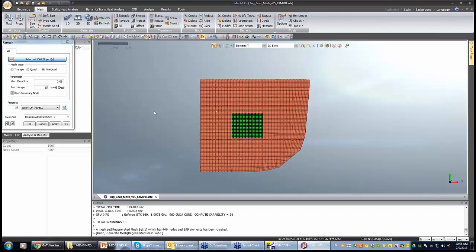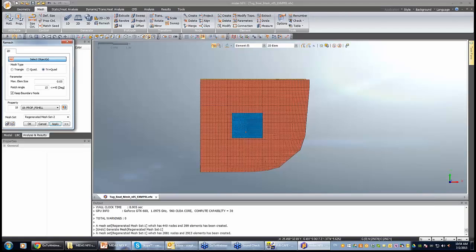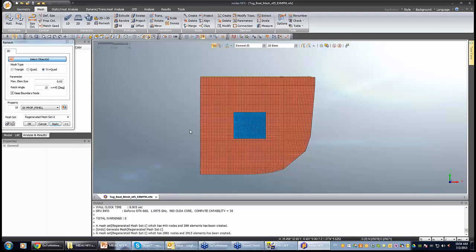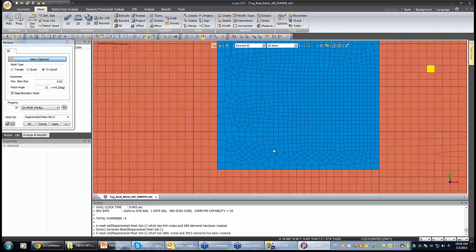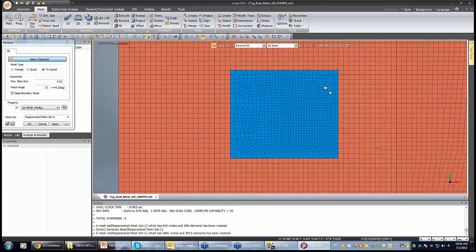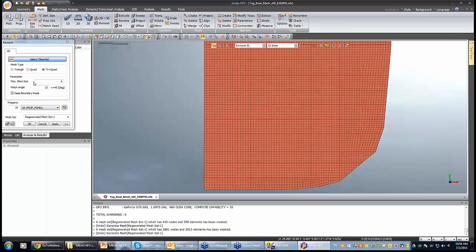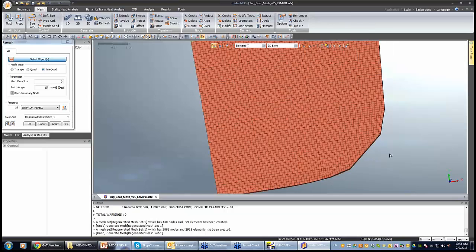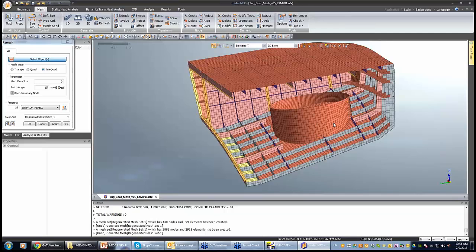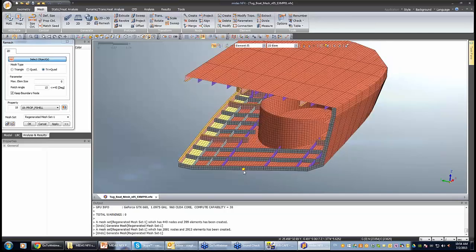So you can see here that according to what we have defined, we have a remeshing part. You can utilize that. You can use your keep boundary node, choose the element size, mesh type, triangle, quad, and tri and quad, and then remesh the appropriate parts. This is something that can be done either in Midas NFX, or a model can come directly, let's say, updated through BVB CAFE and import it again into Midas NFX, having the same boundary conditions as defined and being rerun at the end.